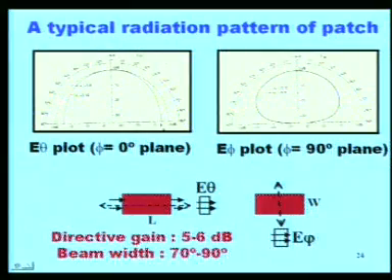At theta equal to 90 degrees, it is something like 5 dB down for the case which is epsilon r 2.32. So, here it shows the effect of the substrate parameter on the radiation pattern. For epsilon r 9.8, which is a large one, you do not see any change in the radiated field with respect to theta. Here also it is 0 dB, almost 0 dB.